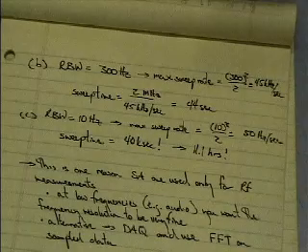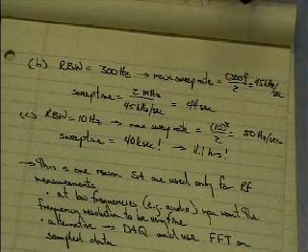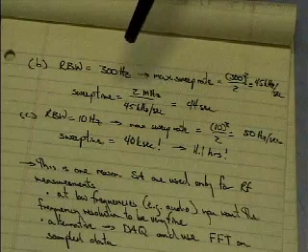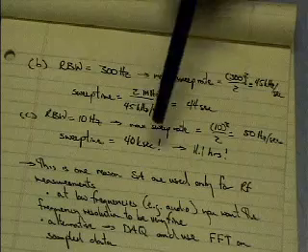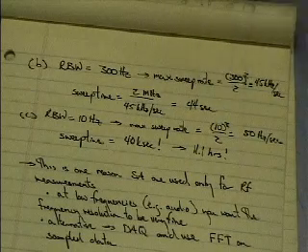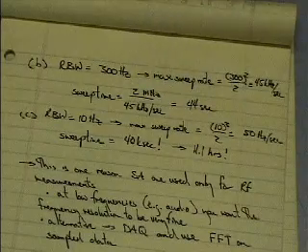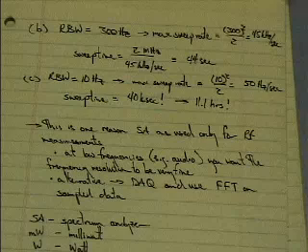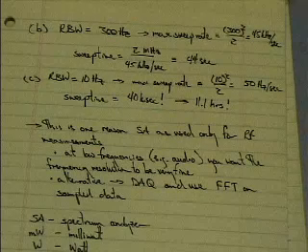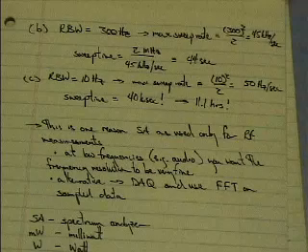So the bottom line is that when we are looking at very fine resolution, on the order of hertz, we need to do a couple things. One, either look at a very narrow band, not a 2 megahertz chunk but something very small, or use an alternative method. And the main reason spectrum analyzers are not used for audio signals is basically because of this res bandwidth issue.